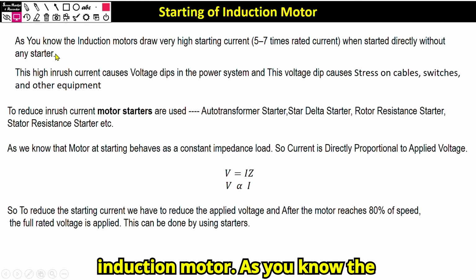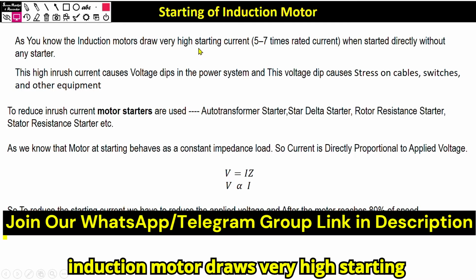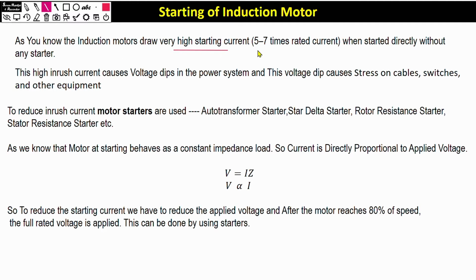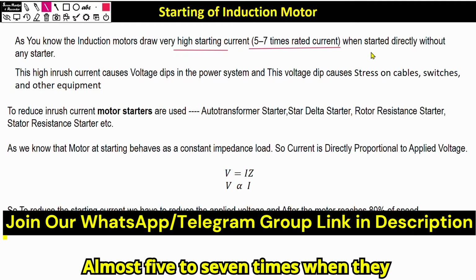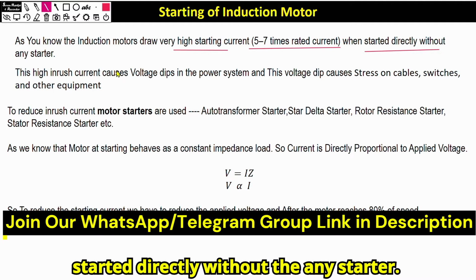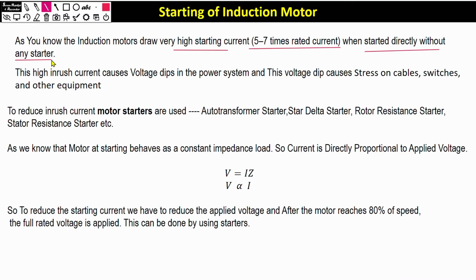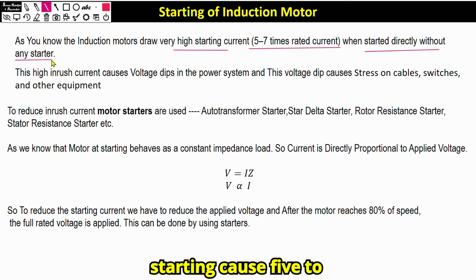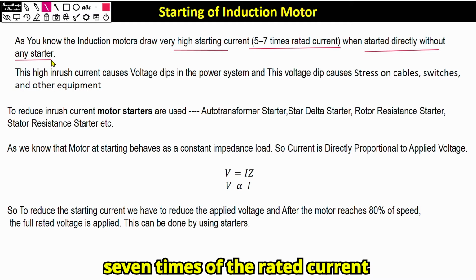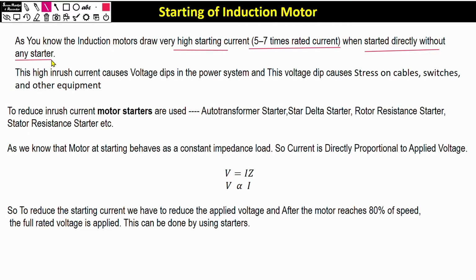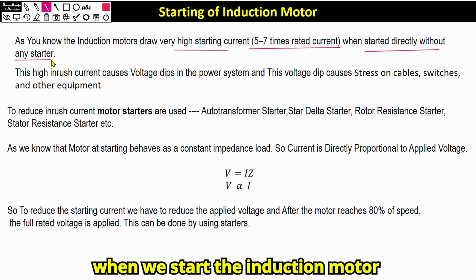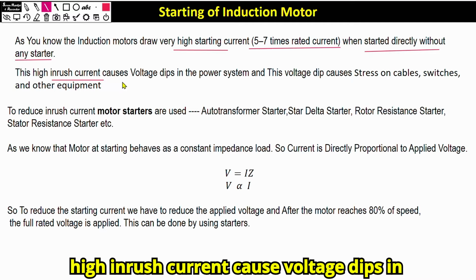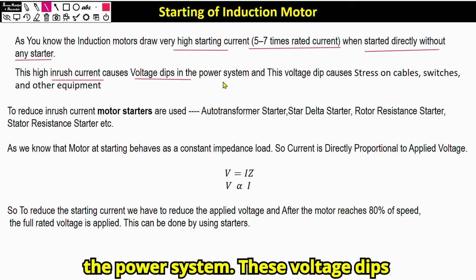Induction motor, as you know, draws very high starting current, almost 5 to 7 times the rated current when started directly without any starter. This high inrush current causes voltage dips in the power system.